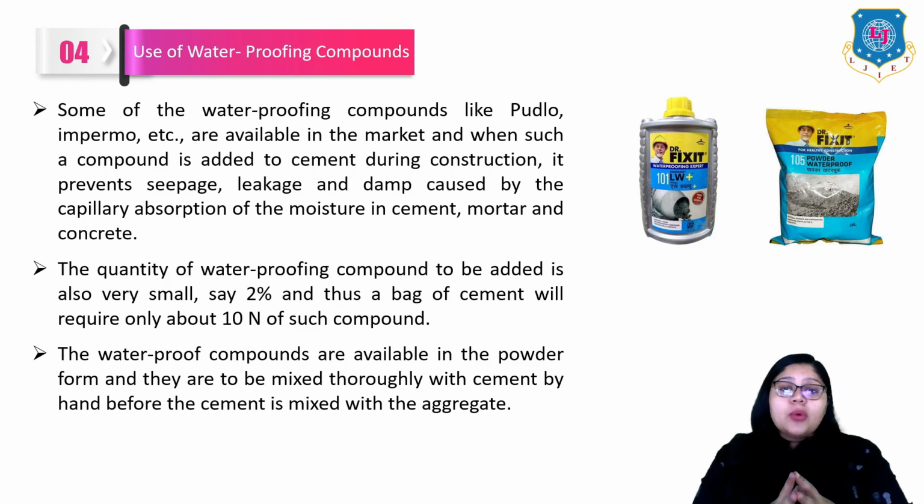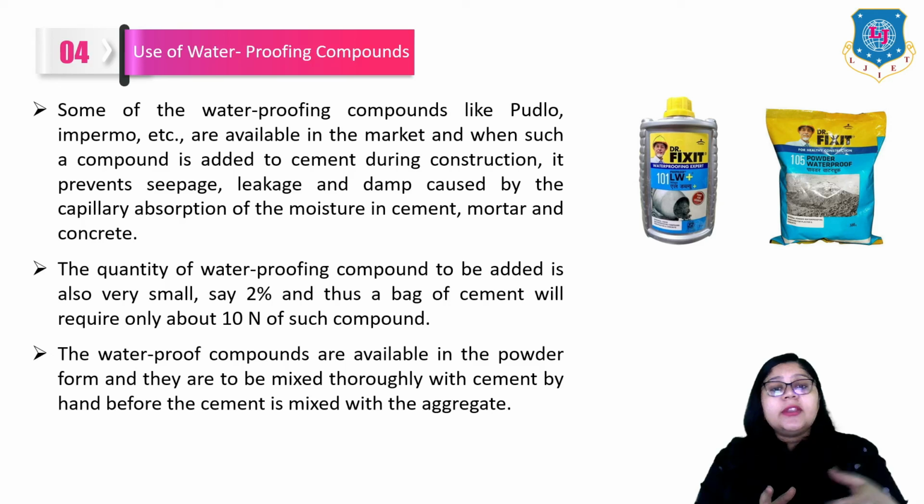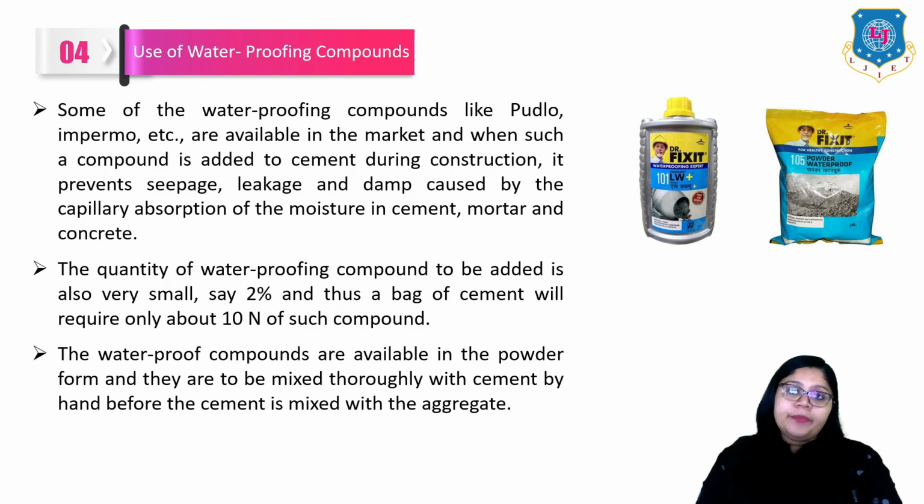The waterproof compounds are available in the powder form and they are to be mixed thoroughly with the cement by hand before the cement is mixed with the aggregate. Here you can see the Dr. Fixit is one of the examples of this kind of waterproofing compounds.